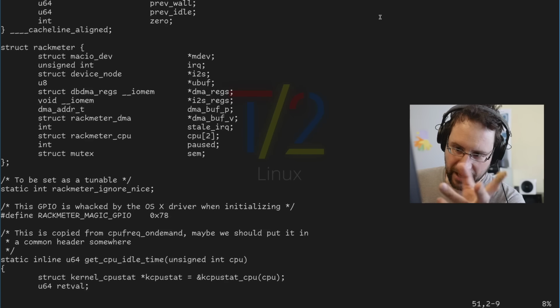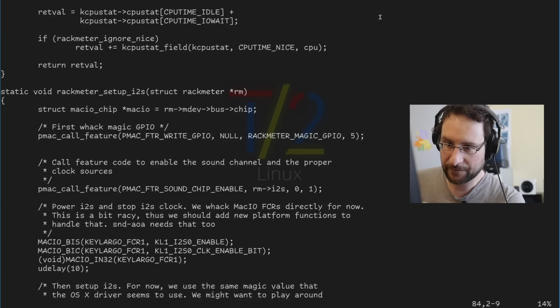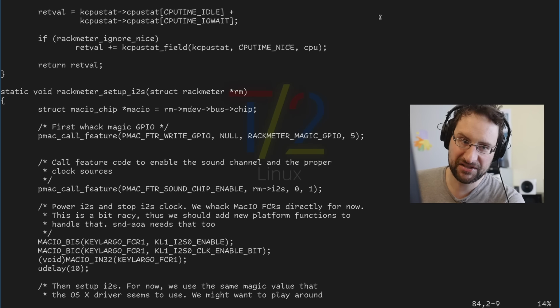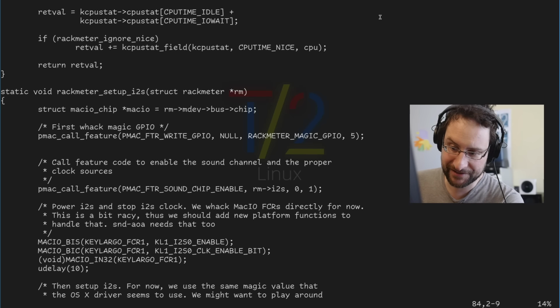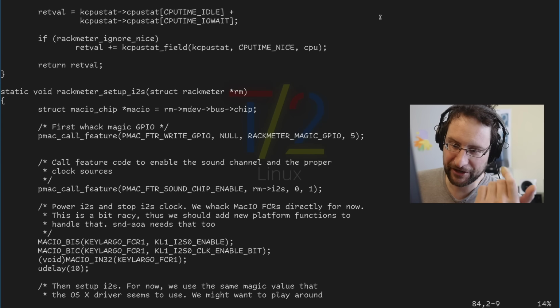And yeah, that's the only other driver that is sampling CPU load. And so obviously we want to reuse it. So as I said in the introduction, absolutely crazy, this G5 VU meter is using I2S audio, I2S for I squared sound. It is sending the VU meter LED data by I2S sound audio protocol stuff.